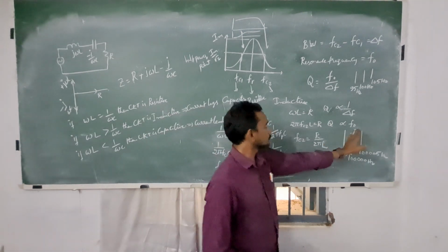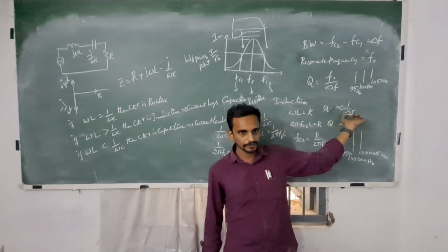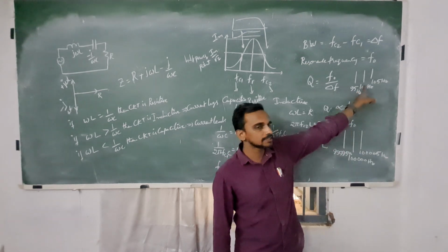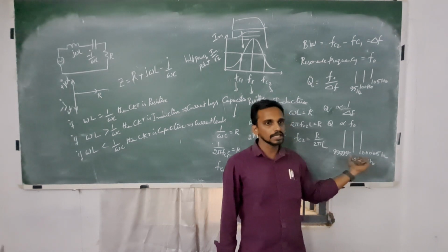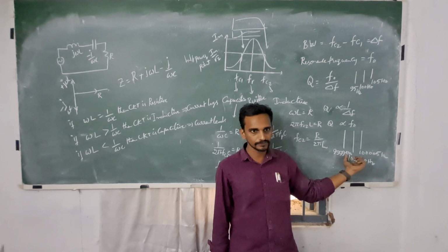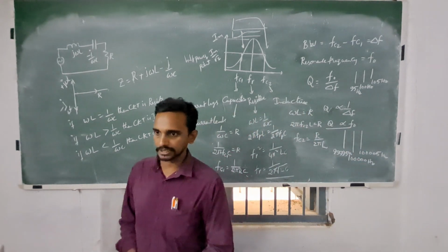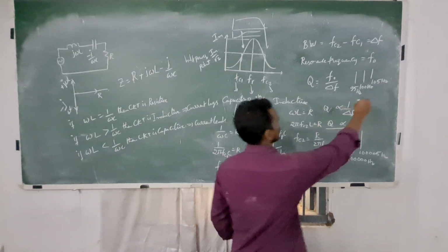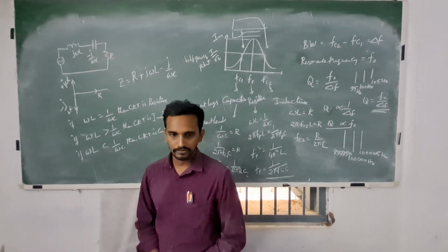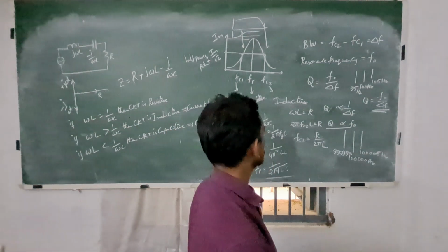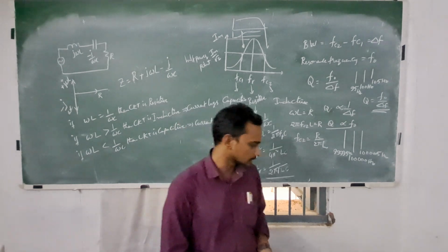So if the resonance frequency is very large, a moderate amount of bandwidth is tolerable. When I select 100 hertz, a bandwidth of 10 looks like a very large error. Whereas if I select 1 lakh, the same bandwidth of 10 hertz seems negligible. So the quality factor is directly proportional to the frequency you are selecting. So in total, the quality factor is F naught by delta F. Actually, these bands of frequencies carry the actual information. We'll see those details later, whenever that comes.